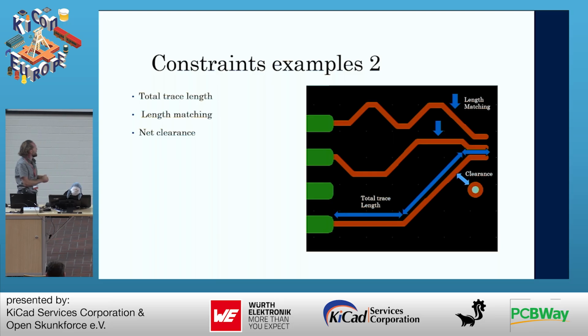where, as in the example here, you have a via and a trace, and what should the clearance between those two nets be? You can have a general constraint saying what the clearance between two nets can be, but you could also say, let's say the via is in one net class and the trace is in another net class, is there a specific clearance requirement for those two nets? Let's say there's noise in one of the signals and you don't want that noise to contribute to anything in the other signal. Well, then you might want to add clearance between those signals to avoid that.